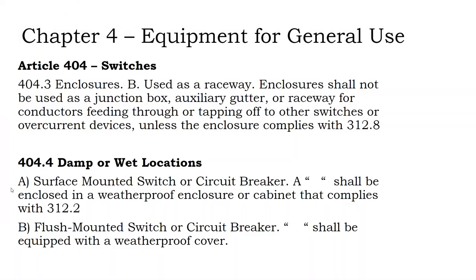So, damp or wet locations. We have to make sure that if it's in an outdoor environment, if it's wet, if it's underneath an awning, that we're using wet rated boxes.